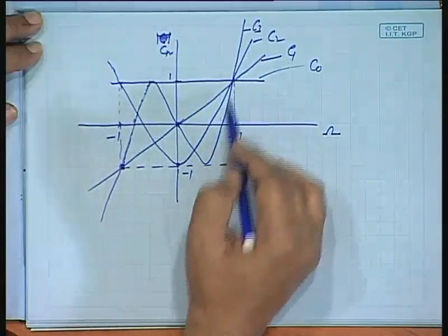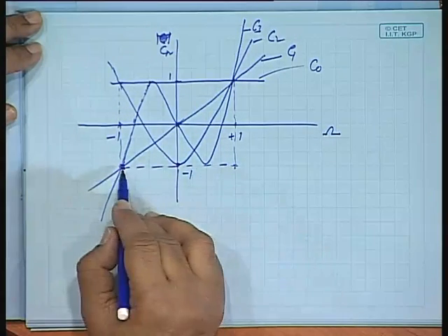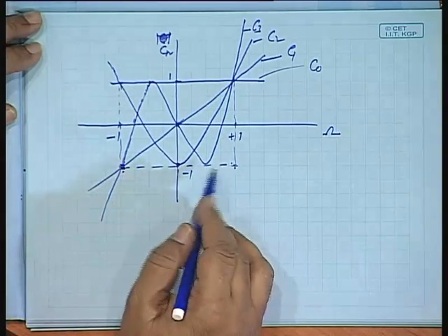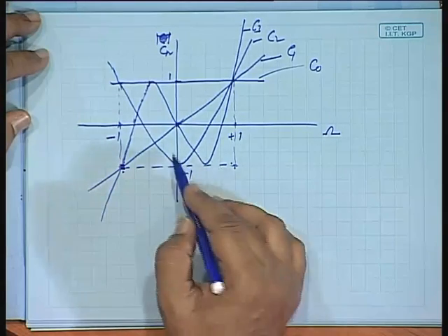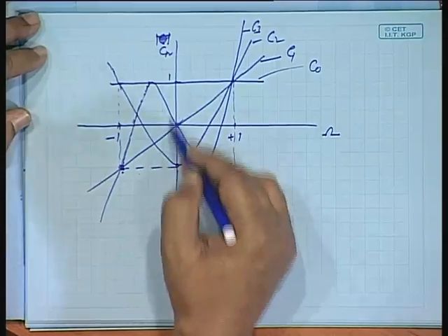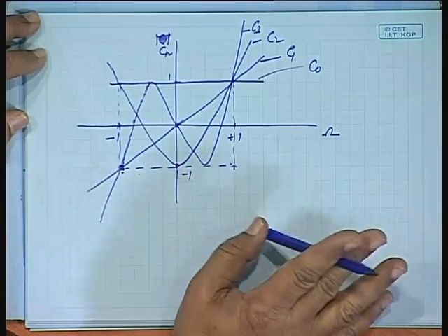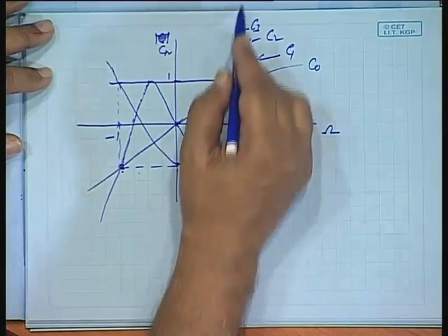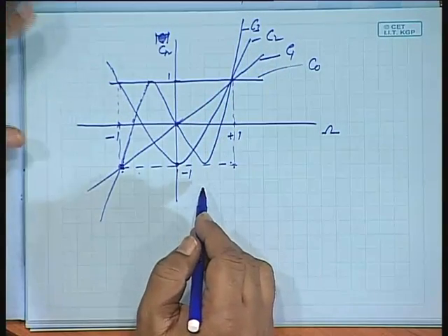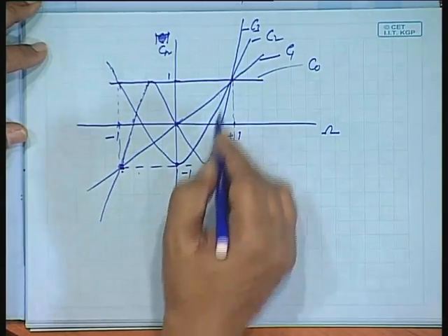You will find a Chebyshev polynomial has this important characteristic: within the range minus 1 to plus 1 for x or for omega, the function c alternates between minus 1 and plus 1, and then after that the magnitude goes up like this. The higher the order, the faster the growth in magnitude, either to the negative side or to the positive side.